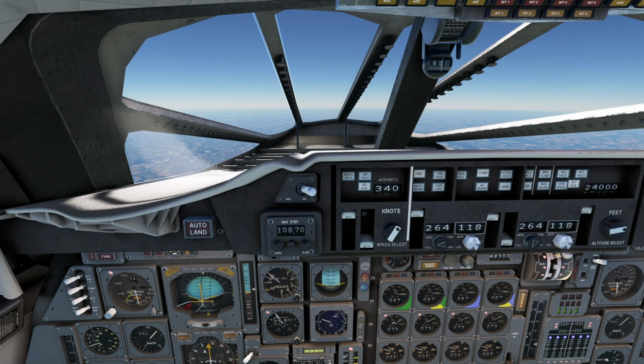We are at flight level 240, 340 knots. We have to start our trim. We need to trim the plane back so we can accelerate and climb. We're going to turn on the afterburners, go to max power and engage the autopilot mode max climb, which should bring us to about 45,000 feet at Mach 1.7, where we're going to turn off the afterburners because at this altitude and speed they don't contribute anymore and just use an enormous amount of fuel.